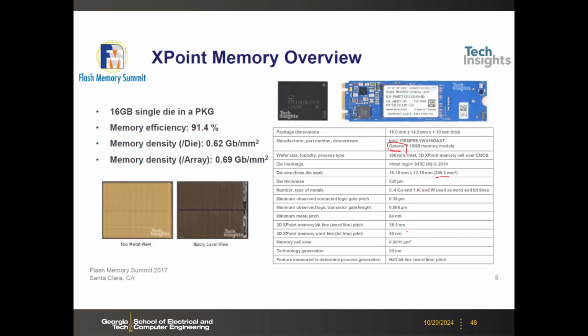And what we care about here is the pitch, which is about 40 nanometer. That means the half pitch, which is F, is 20 nanometer. That is the wire width we just talked about: the word line and bit line wire width is 20 nanometer. Pretty small. It enters the region where, if it scales further, the resistance will increase exponentially. It's just at that boundary.